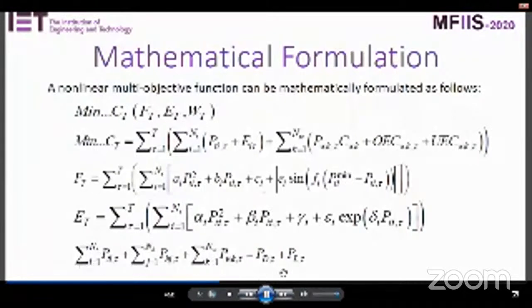The last equation involves the constraint that is encountered in power system power balance. It is evident that the constraints related to short-term hydrothermal wind generation scheduling are mainly operating limits of the concerned generator limits, volume of storage reservoir, discharge limits, constraints involved in water balance criteria, and power balance constraints, which is indicated by the last equation in this particular slide.